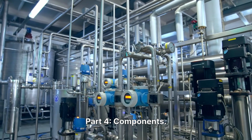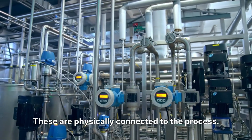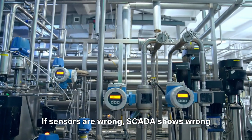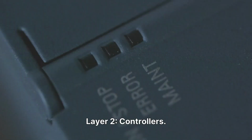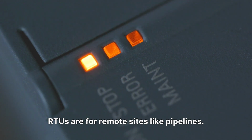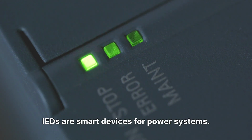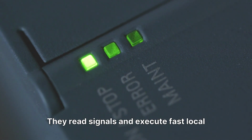Part 4. Components. Layer 1. Field instruments. These are physically connected to the process. If sensors are wrong, SCADA shows wrong info. Calibration is vital. Layer 2. Controllers. PLCs are for factories. RTUs are for remote sites like pipelines. IEDs are smart devices for power systems. They read signals and execute fast local logic.